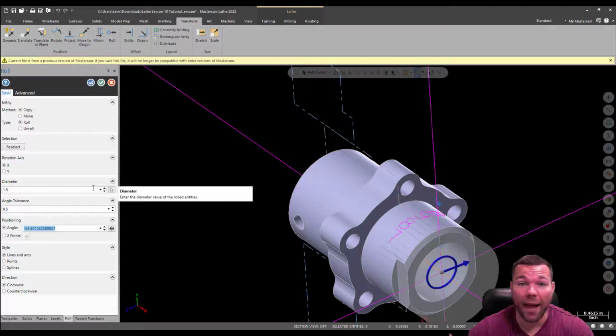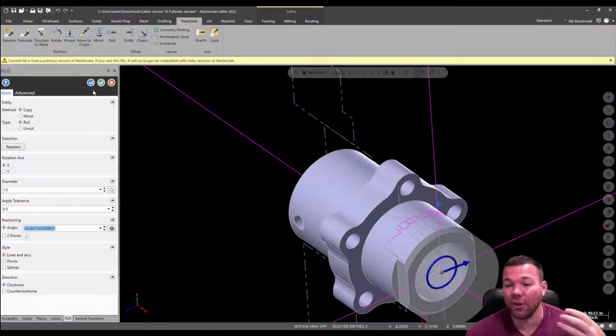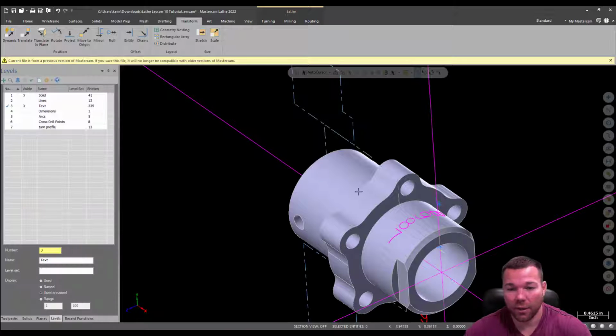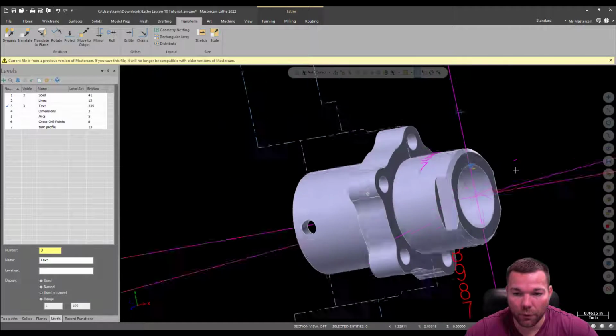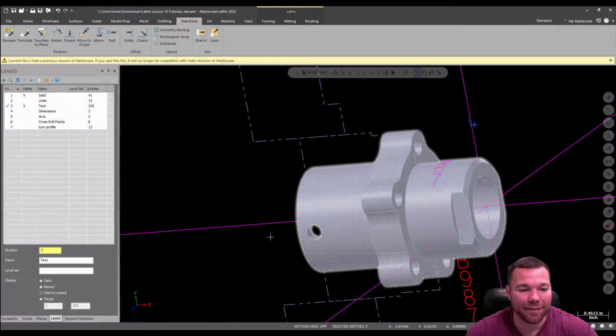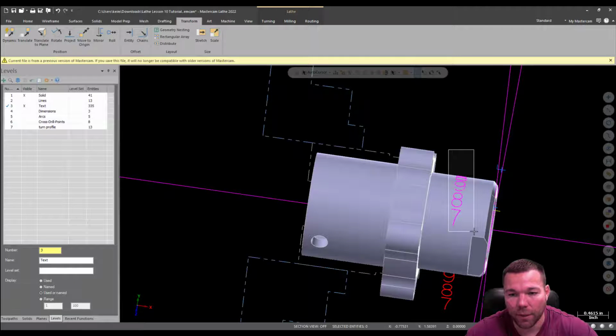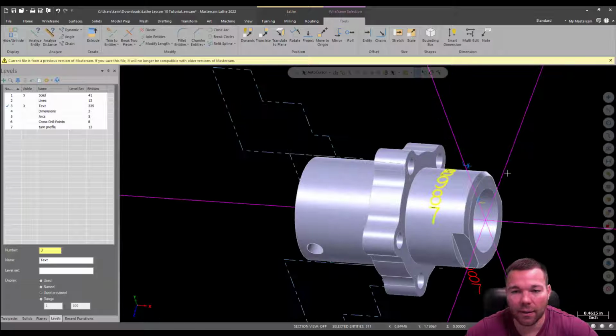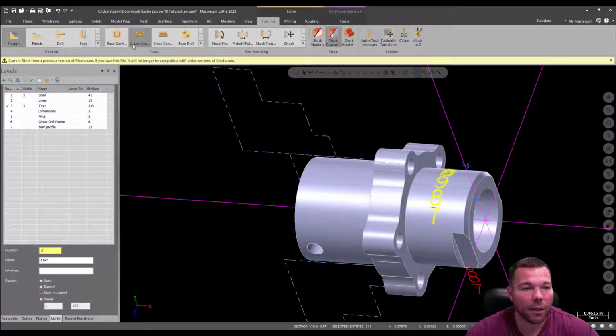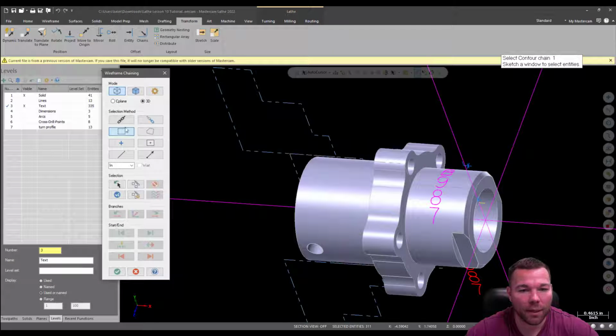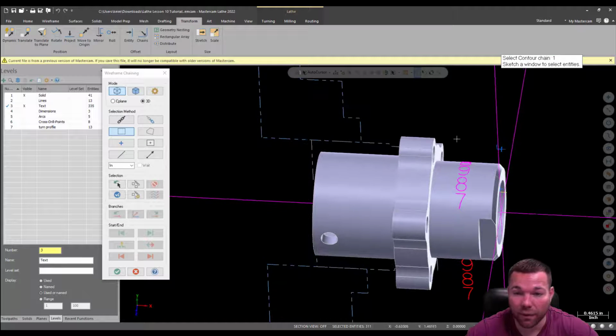If we use that, then we can go ahead and just select our C-axis move here. So it copied. I should have actually selected move, but that's all right. We'll have two copies of it. So I'm going to select that, and I'm going to go to turning, and we're going to do our C-axis contour. And I'm going to select it again because I can't select it before. I'm always in a habit of doing that.